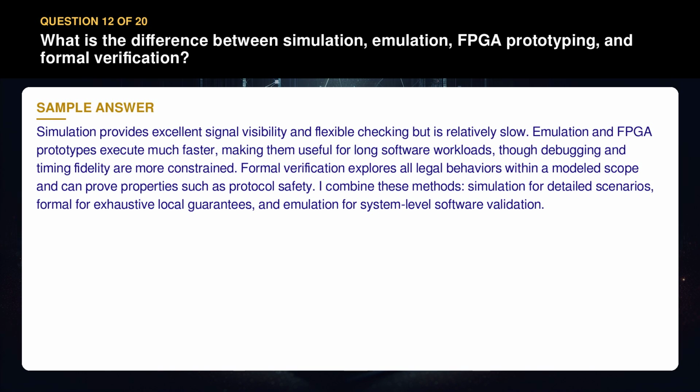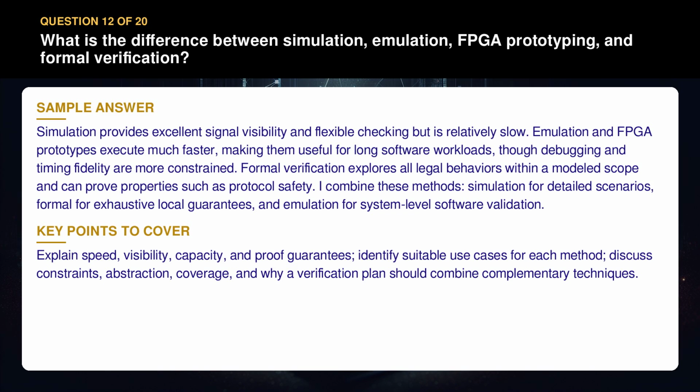I combine these methods: simulation for detailed scenarios, formal for exhaustive local guarantees, and emulation for system-level software validation. Explain speed, visibility, capacity, and proof guarantees. Identify suitable use cases for each method. Discuss constraints, abstraction, coverage, and why a verification plan should combine complementary techniques.